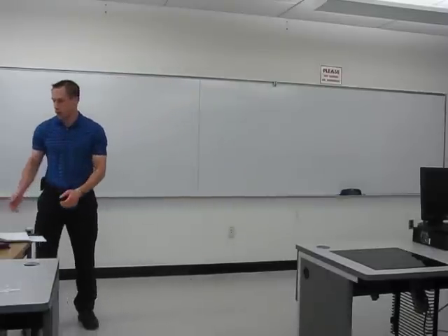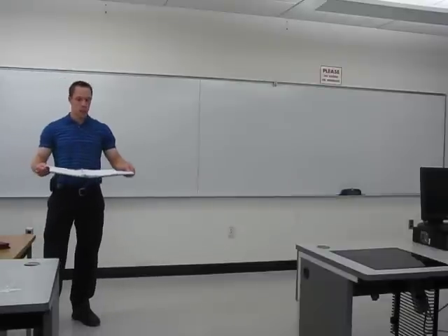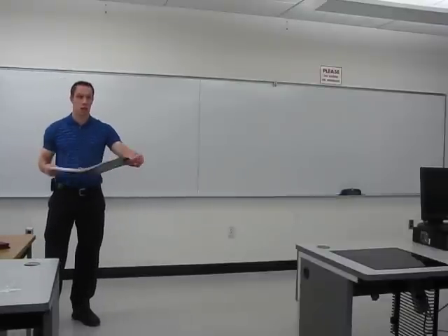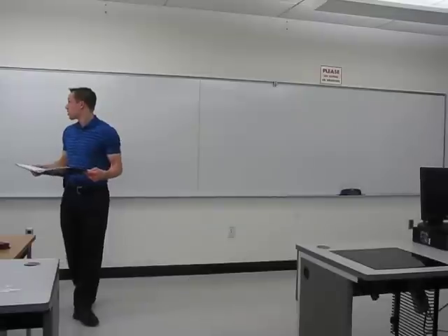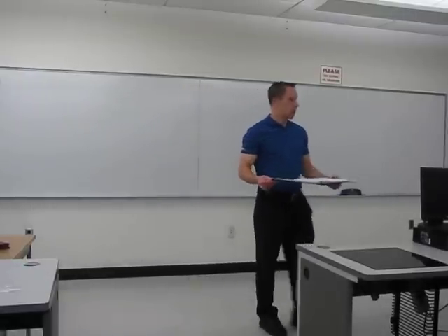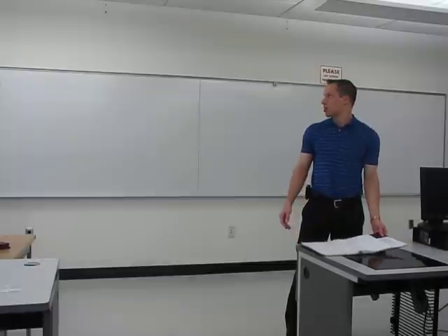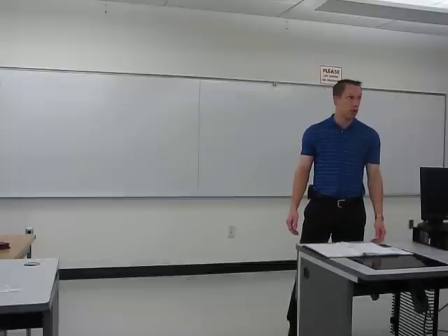They can have the translation motion, where the entire rigid body is translating one way or another, but can also have rotation motion. So it's no longer going to be sufficient to say that the rigid body is in equilibrium if and only if the sum of the forces is equal to 0. Because let me show you, I can have the sum of the forces equal to 0, but my rigid body won't be in equilibrium.